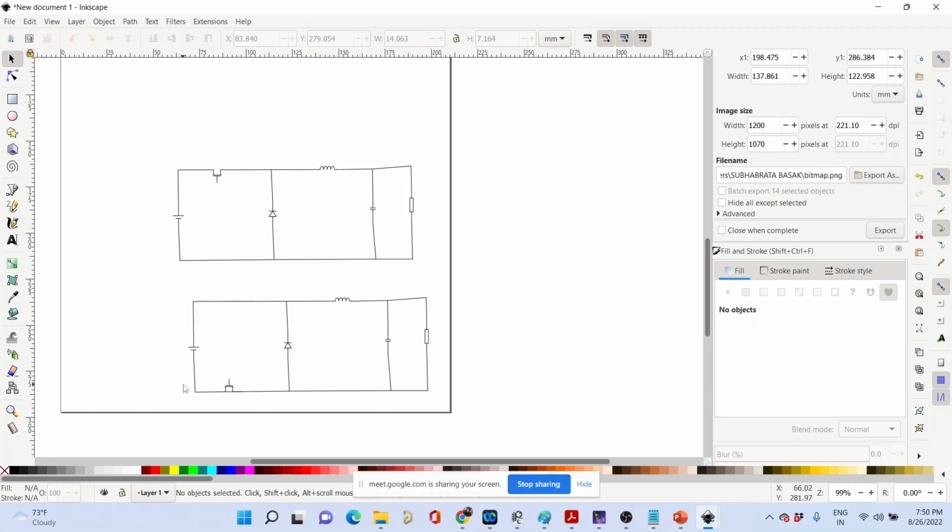So if I consider this as 0 volt, my reference voltage point, and this is ground potential, then whatever voltage you apply, 10 volt maybe, without any confusion you can say that there is 10 volt across this. However, at this point you cannot confidently say that this is 10 volt, because you do not know what potential this point is at. This point may be at 5 volt, it may be at any other potential. In that case, proper turn on of the MOSFET would be difficult. Are you getting my point, everyone?